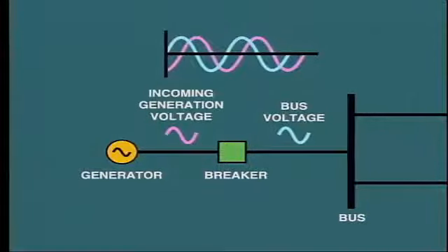You can see that the generator is over 90 degrees out of phase. If we closed the breaker in this situation, the generator would attempt to pull itself into phase. Now, this could twist the windings in the stator core and create considerable damage. Of course, the great surge of power would be detected and the breaker immediately opened by protection devices.